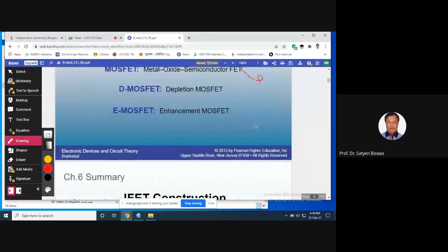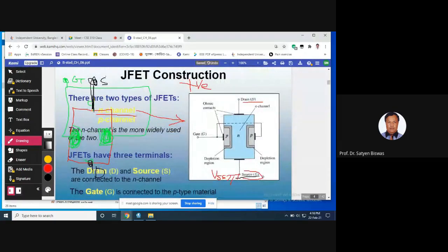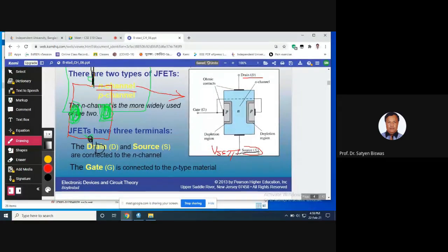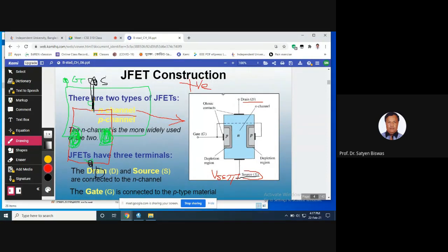But in this case, there is no collector, no base, no emitter. Here we have a source and a drain. So we call the bottom terminal VSS, and the top terminal VDD. This side we call VDD because of the drain, right? In the case of FET, from now on, all kinds of circuits have VDD at the top and VSS at the bottom. VSS, because this is the source, and the source is the n-type, whose electrons come from the ground. That's why this is on the bottom side.